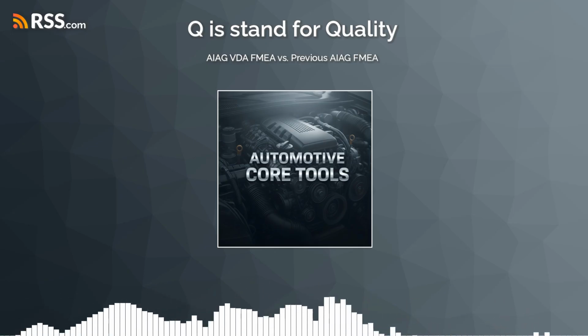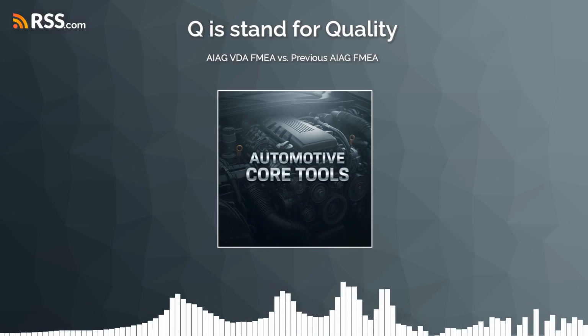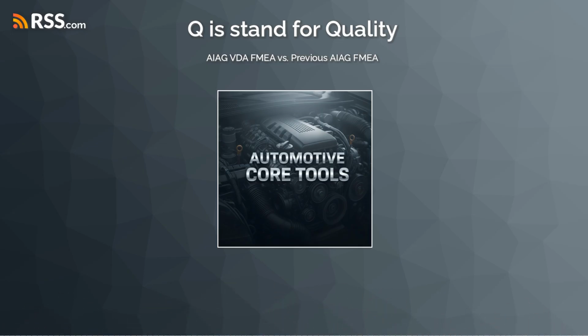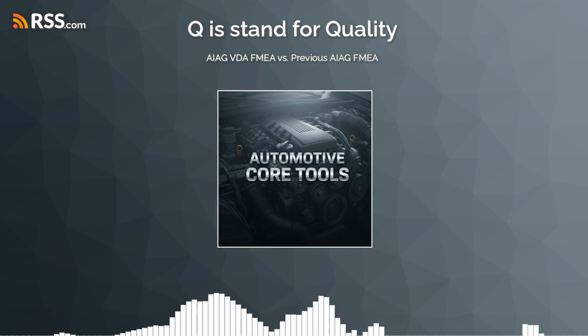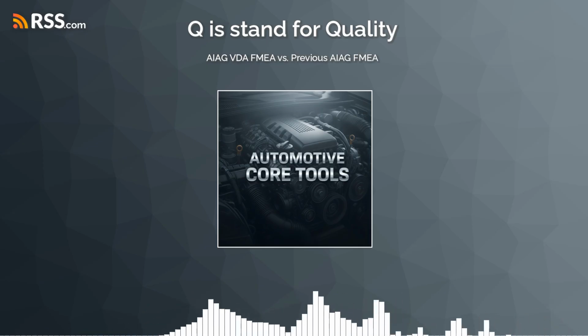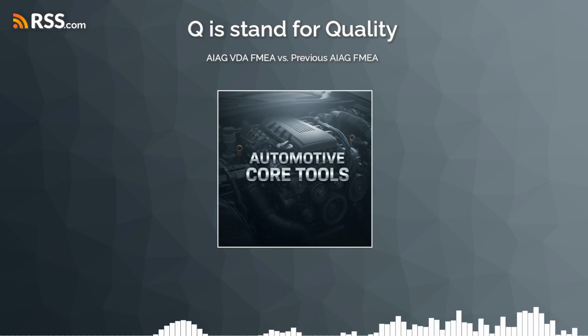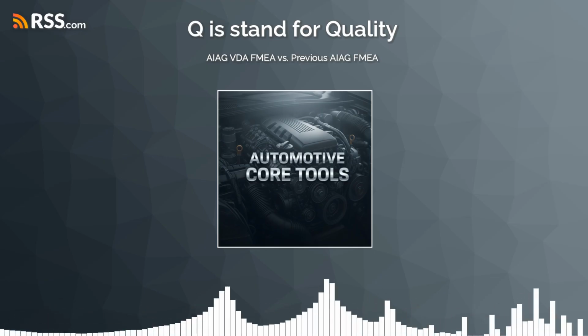So how does the new AIAG-VDA method tackle that specific problem? So they moved away from that single RPN number entirely, and they introduced the action priority, or AP, method. AP, yeah? This is more of a qualitative assessment. It's focused on criticality. And the crucial philosophical shift here is that it gives absolute precedence to the severity of potential failure. Severity first. Severity first.